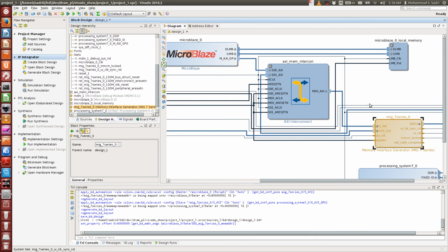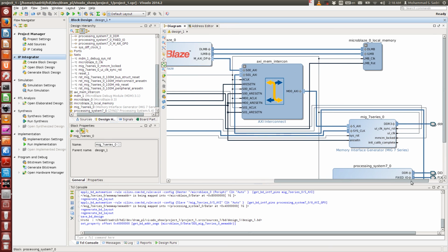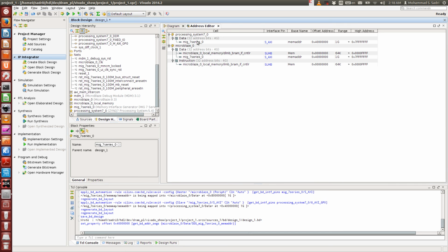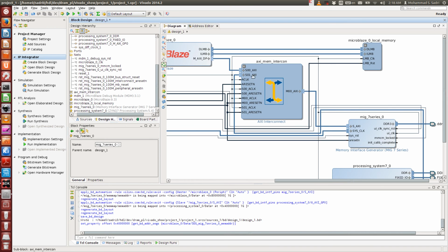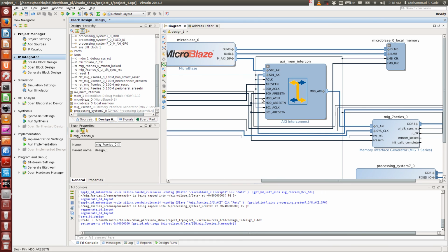Or you may ask a lot of other things. For example, you may ask, what if I wanted to change these addresses on the fly? I mean, up to now we have some addresses, and from now on I want to have other addresses. Yes, again, this is possible. This interconnect that you have here has a fixed address decoding logic, but it's possible by adding suitable interfaces here. But for now I don't think we need that.